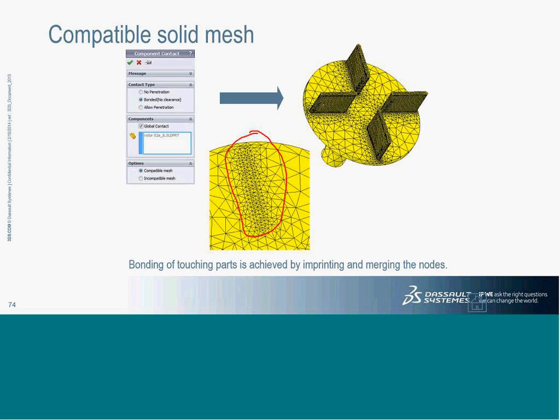It is such that it is a coincident node, but actually there will be a single node that will be shared between these two parts. Now these two are different bodies or parts connected using bonded contact. It's not a single body, whereas in simulation it will be connected using bonded contact and the connection is complete. The compatible option is used where a single node comes into the picture and shares the connection between these two.